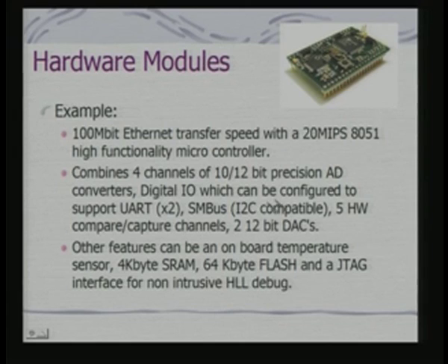If you see, it has I2C compatibility. So, using the I2C, you can connect it to your main system and have data transferred to this kind of small footprint device, so that you can plug your appliance through this card to an Ethernet port and have Ethernet enabled connectivity. Now, in this case, the basic protocol gets implemented on the processor.